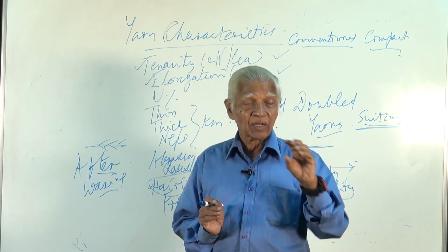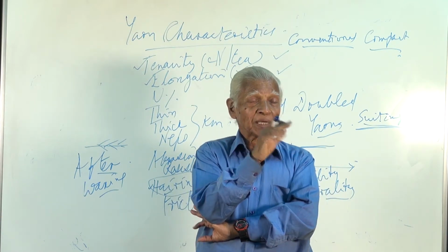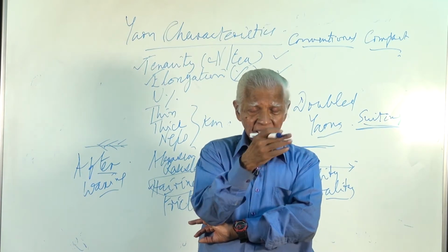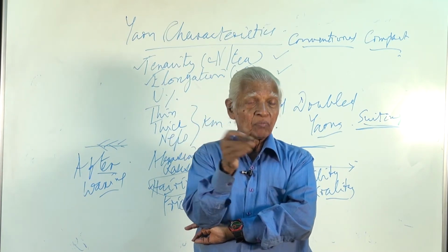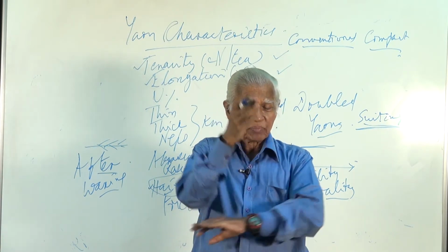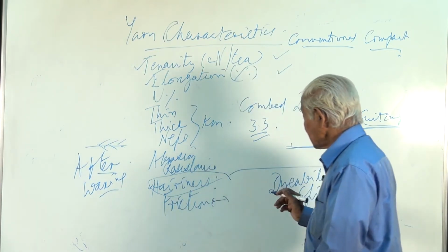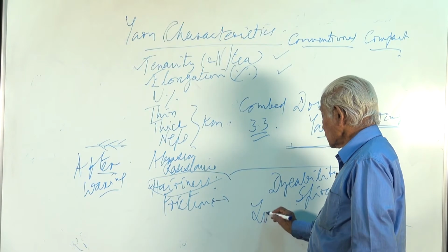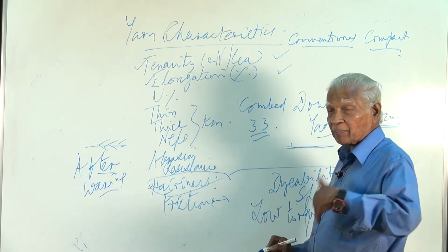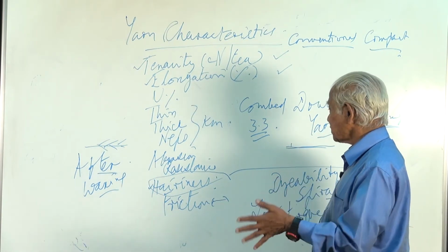Knitted fabrics were made from the normal yarns and also the low torque yarns, and the spirality that is present in the fabric made from a conventional yarn vis-a-vis a low torque yarn was investigated, and they found that there was a considerable improvement in spirality. That means reduction of spirality was noticed. So it has been well established that a low torque yarn is beneficial to improve the dyeability and also the appearance, and also reduce the defect, namely spirality, in the knitted fabric.